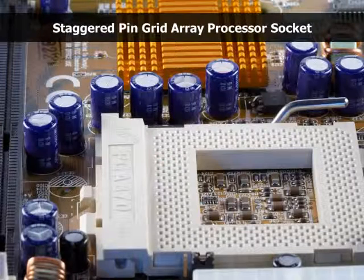Next, you have the staggered pin grid array. You notice here that one row is perfectly aligned and the other is offset from it a little bit, and the other one aligns offset as well. And this is just another type. Pins are staggered, and the idea here was to be able to fit more pins or more connections into the socket mechanism. In theory and in practice, actually making it quite faster.